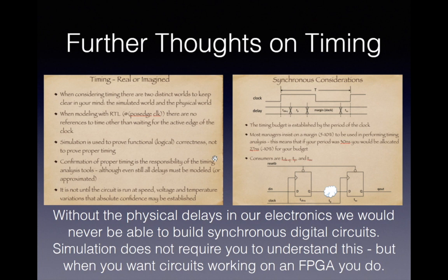The simulation that we run, the goal is to prove the logical correctness, not to prove the proper timing. The confirmation of the proper timing is the responsibility of another tool called a static timing analysis tool. And that'll be the subject of the last third of 360 this semester. And I want to make sure we're ready for it. So that's why we need to catch up here.